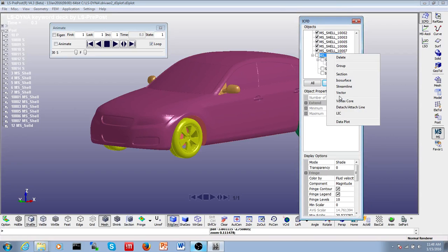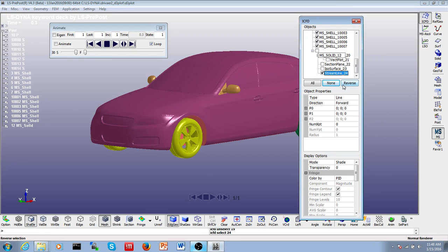So here, just as an example, I'm going to right click, go in the streamline mode here, go plane. I'm going to draw a plane. I more or less know the coordinates by heart now. 0.8, minus 0.4, this will be 1 point. Then the other one, minus 0.2, minus 0.8.